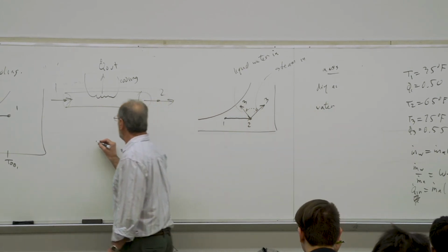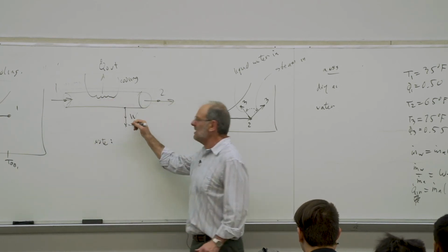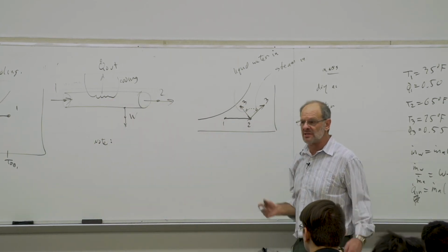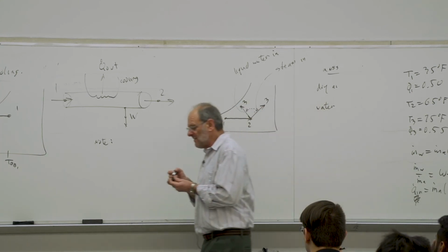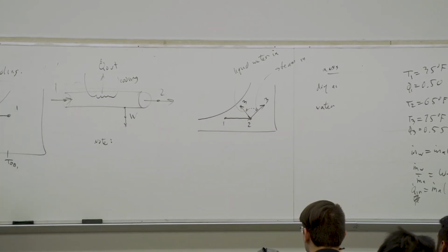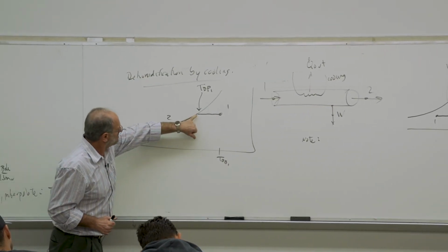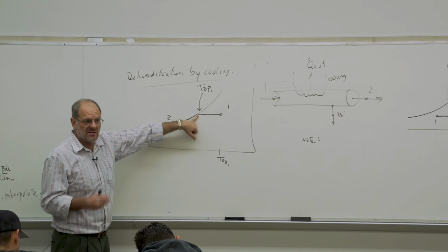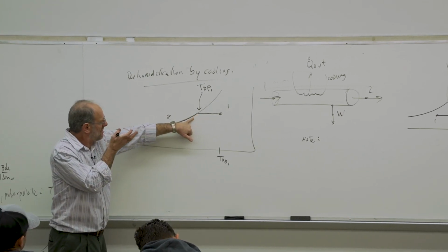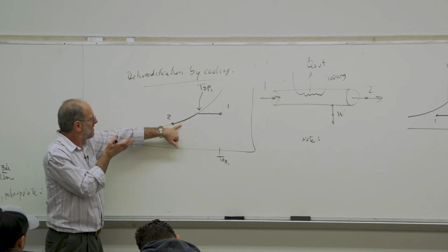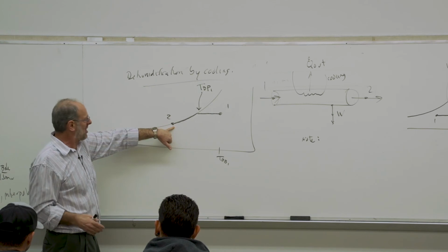Okay. I might note that in your analysis, you are going to need to know what the enthalpy of that water is. However, it's not going to be a constant value. I mean, is it going to be at 0.2? Well, not really. The first of the water that condenses out of the air is going to have the dew point temperature associated with it. But as we continue to cool, and as the dew point continues to drop, the temperature of that drain is just going to keep dropping and dropping.